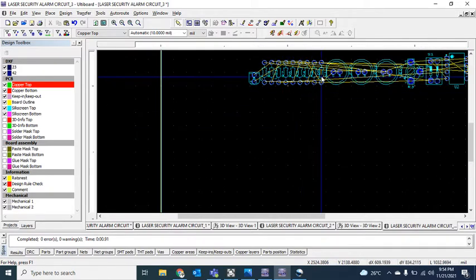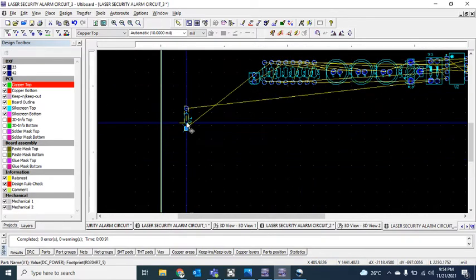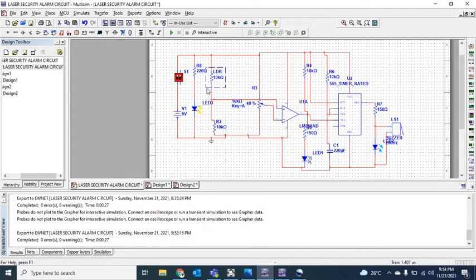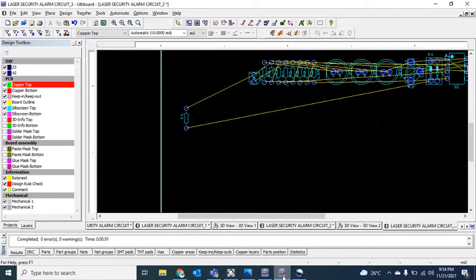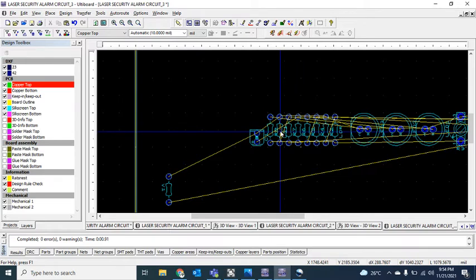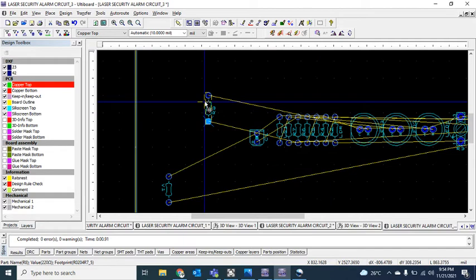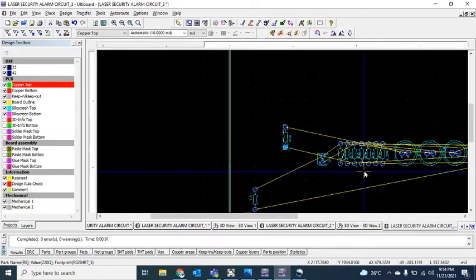Okay, place the power source V1. It will have a name. By using that name, you can identify the components. If you want to turn a component, select the component and press Ctrl R. Then go back to the circuit, R8 and LED3. Arrange them properly. Here is my R8, and sorry, it's R8 and LED3.